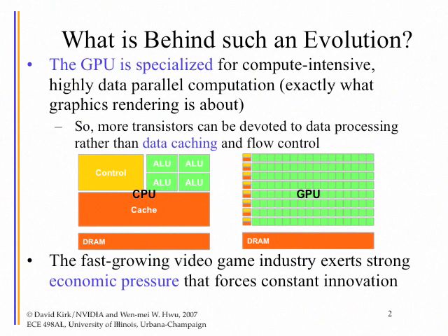If you look at the matrix multiplication example, we will have 256 of those threads. Out of random distribution, you will see some of the threads accessing memory, and some of them will come back with data, and the others will still be queued up in the memory access interface. So as soon as some of them come back, you execute them in the function units. And that's how you tolerate memory latency. And that's why you need to have thousands and thousands of threads in this chip to keep it busy.